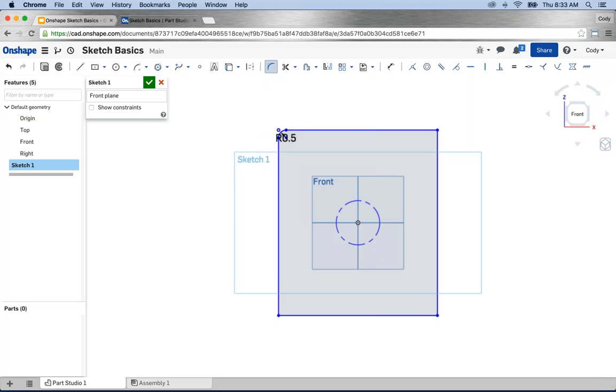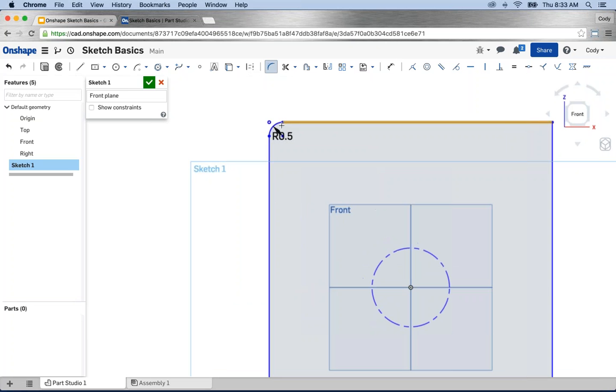Very simple, and all it does in this case is add a 1/2 inch arc instead of that sharp transition. So if all you're trying to do is radius corners in a sketch, Sketch Fillet is a very powerful way to do it.